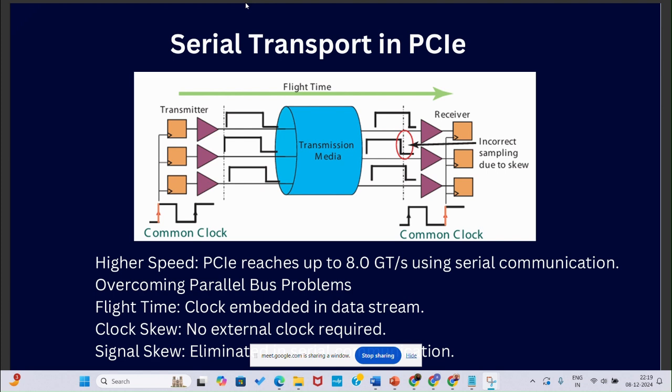The benefit of having this is that we have reduced two more lanes, or physical lane clocks. So the clock is also sent with the data, which is called clock embedded data. We will explain in a couple of days, in the PMA section, there is something called PISO, parallel in serial out. There you will see how the data and clock get embedded. Got it. Sure, thank you.